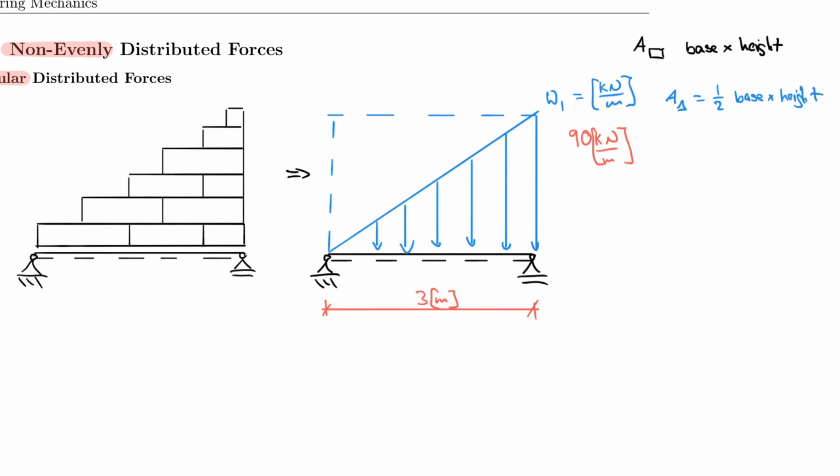And so you already understand how to calculate this, but again, be a little bit careful with this unit here, kilonewton per meter, because again, let's say it's 90, then it's only applicable to this arrow. Here, this arrow would be 0, and everything in between would be somewhere half that way, or a different increment of it. So for example, right at the middle, of course, it would not be 90, it would be 45 kilonewton per meter, if you will.